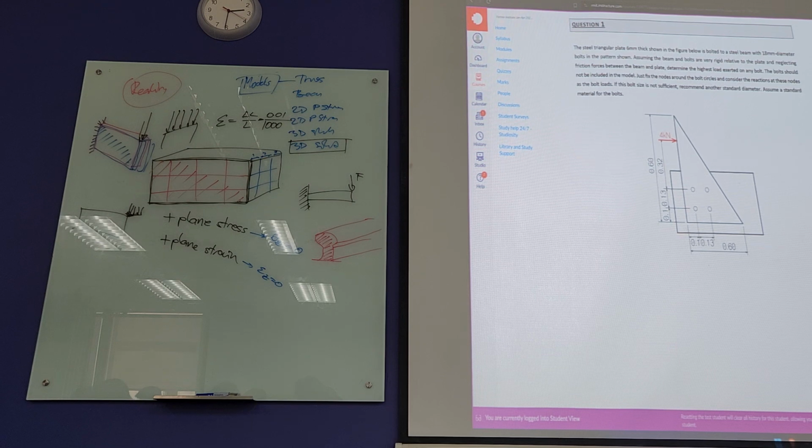So once you've got that sorted out, then you start thinking, okay, out of these potentially 3 components, what am I interested in? Do I need to model that back face or back plate? No. Do I need to model bolts? Or am I going to be just good with the plate that is there? Yeah? And it's the first thing that you need to make a decision on.